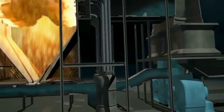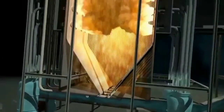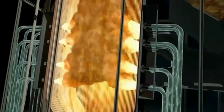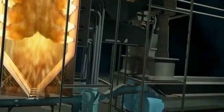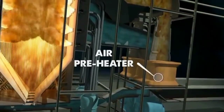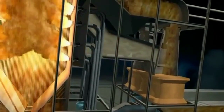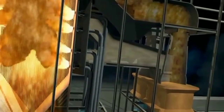A portion is routed to the pulverizers, which crush coal into a fine dust before pushing the mixture up through feeder tubes. The other portion passes through an air preheater, which transfers heat from the exhaust gases to the incoming air, raising the air temperature, reducing moisture, and producing a cleaner burn.